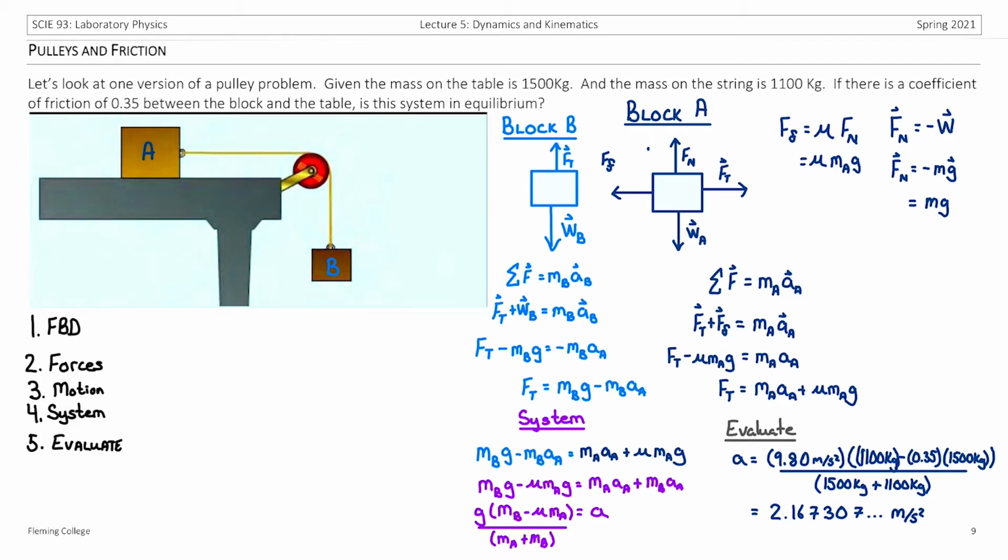And we just want to make sure. So we were solving for the acceleration of block A. So having a positive value in the way we set up our system says that block A accelerates towards the pulley, and we can accept this value. Note that if we had applied the constraint of acceleration way back here to instead solve for B, we would have ended up putting a negative B in here. We would have ended up with a negative value here, which would have told us that block B accelerates down, which also would have been an acceptable answer.